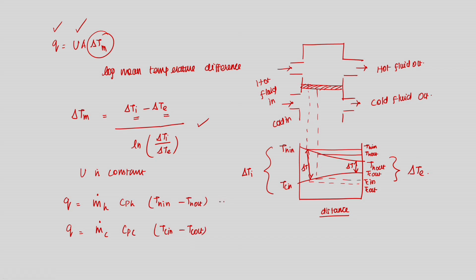Okay. So, remember, one, hot fluid loses heat and cold fluid gains the heat. So, this is the way we calculate and design the heat exchanger, right. So, if I want to know how much heat transfer area is needed to heat my fluid, food or liquid food, I will get to know from Q by U del T m.